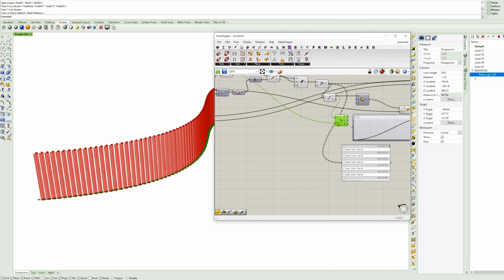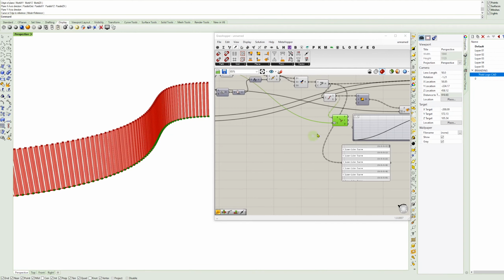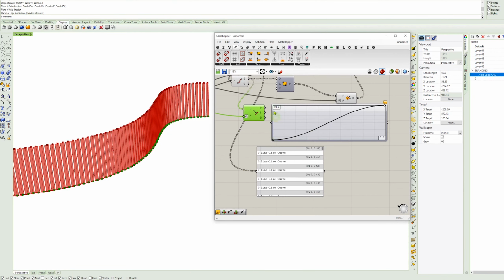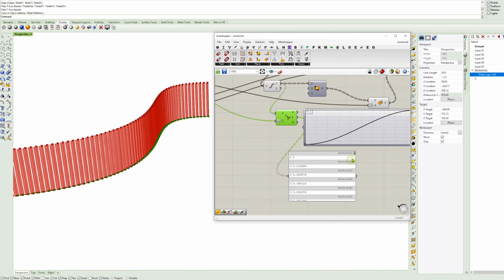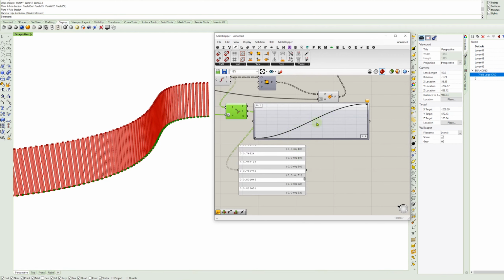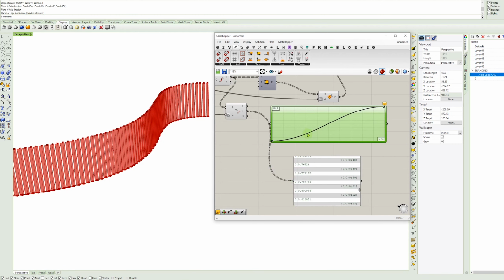And now we can also right click on this and reparameterize. That's going to change it from the actual length to a percentage from 0 to 1, which is what we have here on this domain. So domain X is 0 to 1 rather than the explicit length. And by pulling these down, it translates into that T value. That T value is the percentage parameter that we're talking about. So you can see here, it's some percentage along the way. And so it goes 50% here, and then it goes up to 80% there, and that's getting sampled along this graph mapper, or will be in a second.